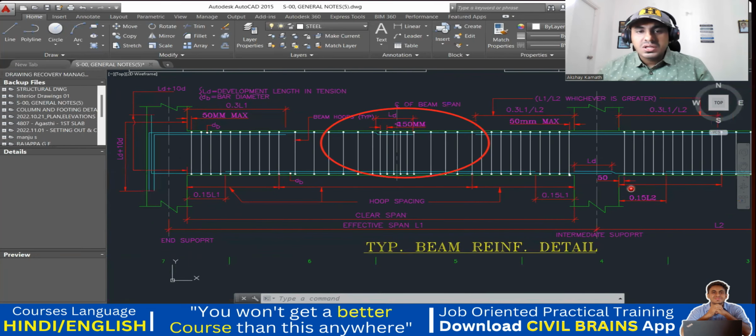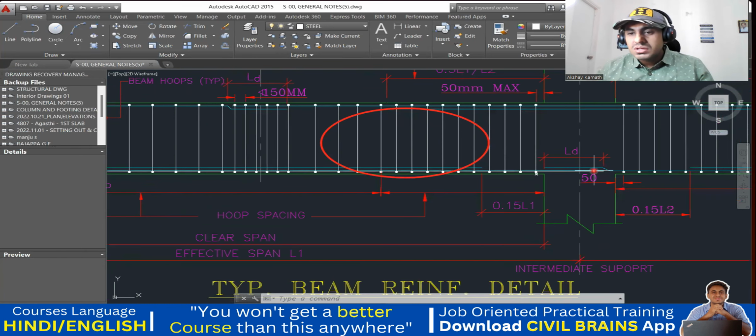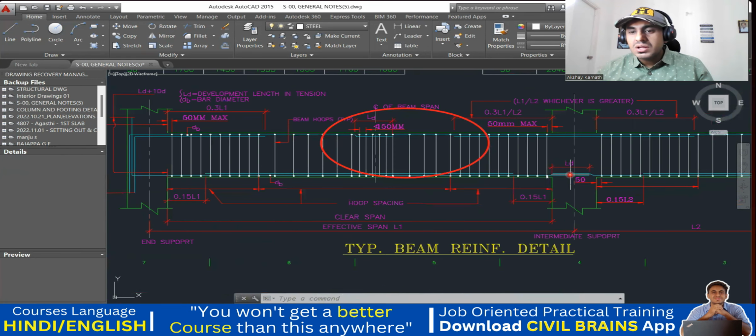I told you the bottom bar should be lapped within L by 4, but here there is no lapping. You can see this bar, see here, they have lapped it inside. Why? Always remember you can do the lapping within L by 4. Usually, if you lap it where the column and beam intersect, in between that, that is good.